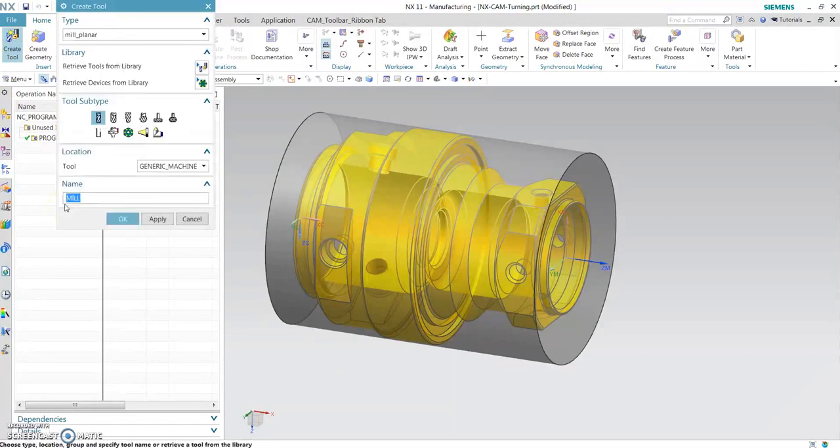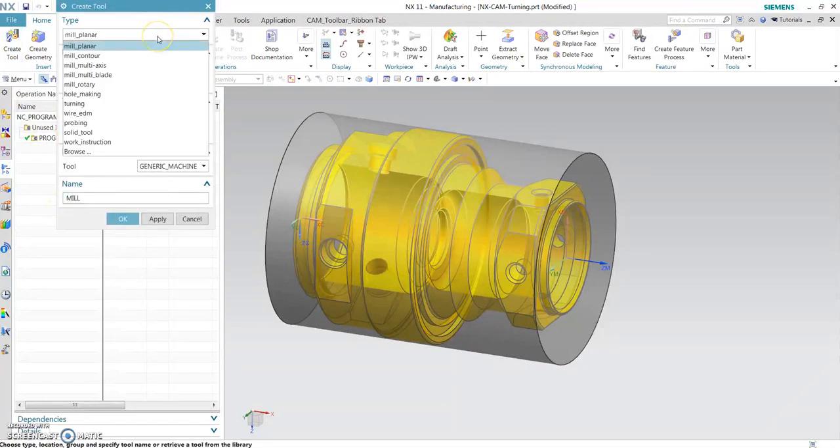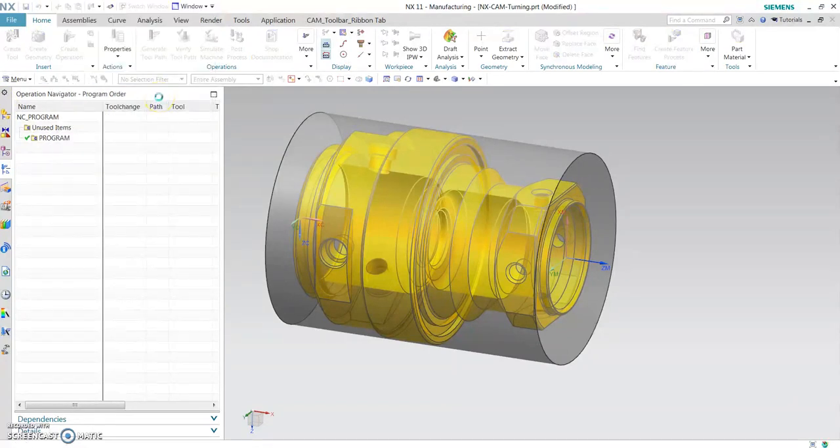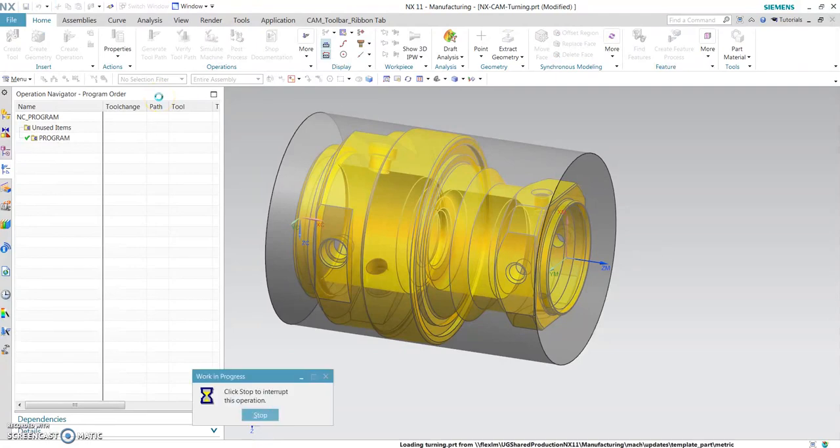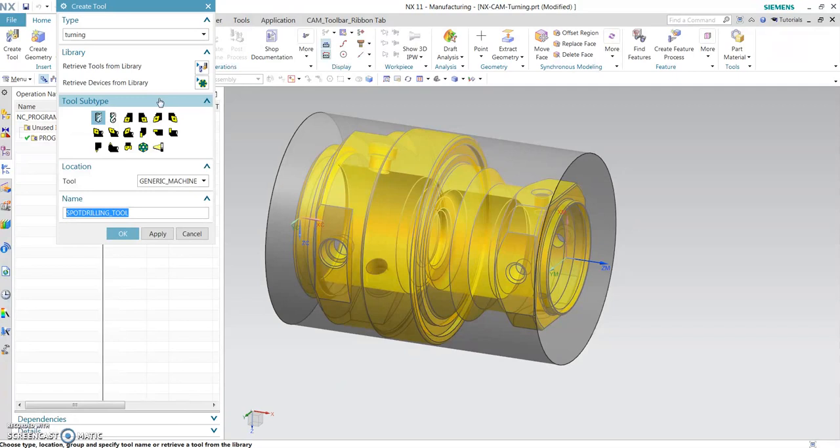Tool. Let's talk about the tool geometry for turning. For roughing, you need to remove a lot of stock. Let's select a CNMG or a CCMT if you want a positive rake. I will go with the negative rake, because we need to remove a lot of stock fast. So let's go with the CAM cycle for roughing.